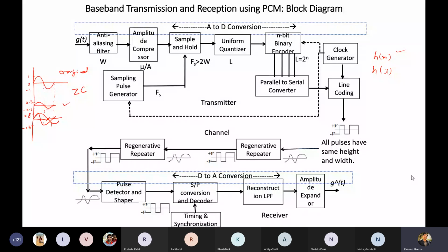Like for example, in fiber optics as channel, there is something we call dispersion. Dispersion happens. Okay, it is a very common physical term, dispersion. So because of dispersion, what happens? Your actual signal gets spread out. So if the actual signal was like this, it gets spread out like this, because different wavelengths of light travel with different speeds in the fiber optics.